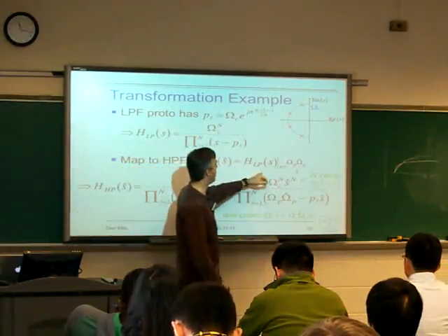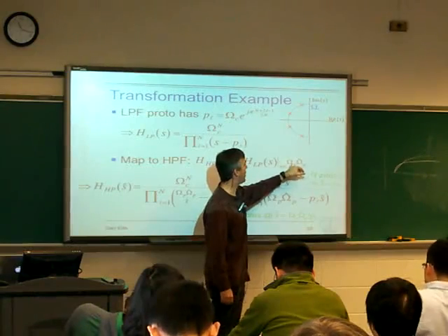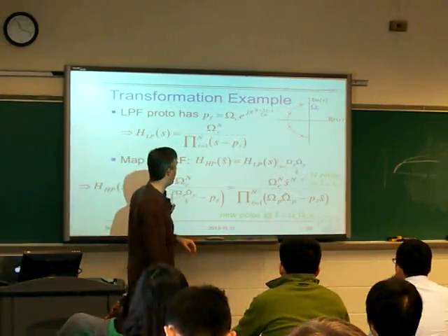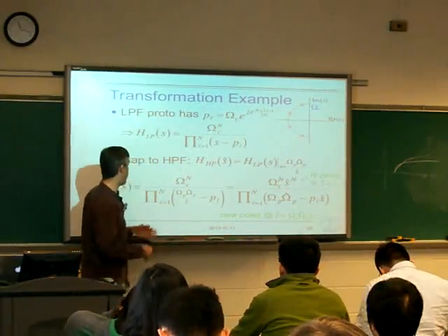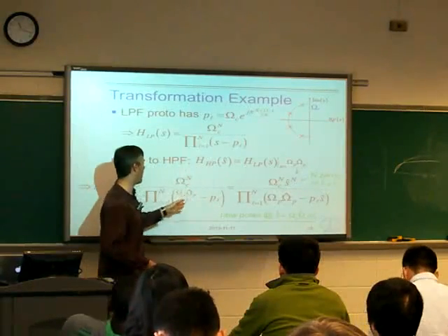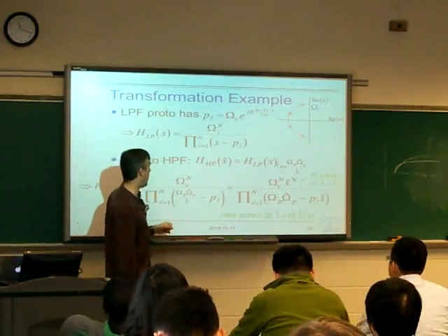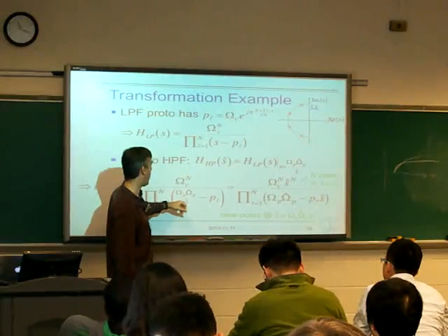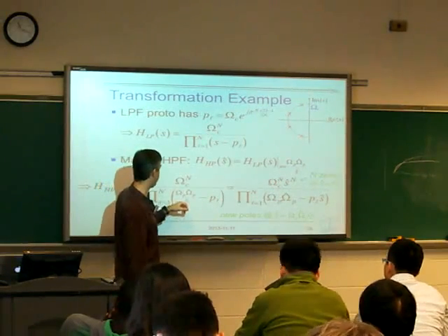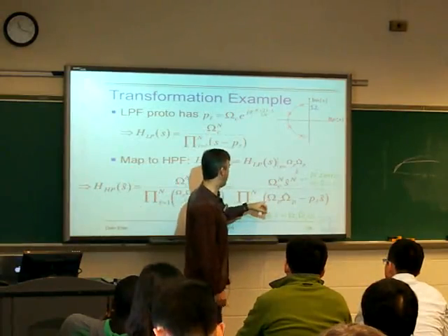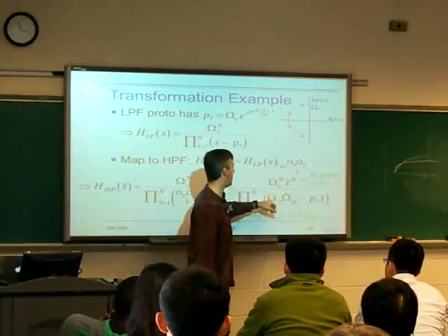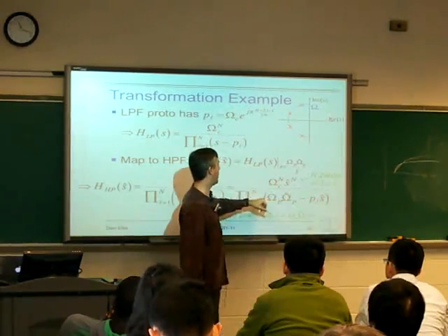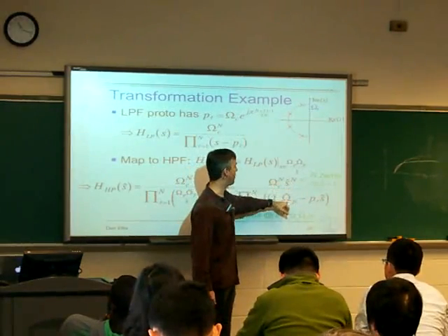When we substitute in s equals omega hat p on s hat, and then rearrange to get a new polynomial, we just get this coming out, which if we multiply through by s hat to the n, we get the actual zeros coming out here, and we also get the poles coming out here.